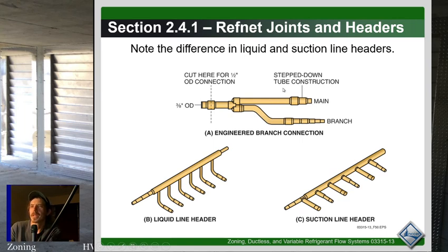Another note on these connectors, I don't know if we discussed last class, is you see how the piping is a size and then it goes up and then steps down and steps down. This is the only time where that's super acceptable in refrigeration. Sometimes your vertical piping is sized different than your horizontal piping in refrigeration, but all these up and down, sometimes you have another reducer that goes back up to another size at the end or something. Don't get too concerned about how pipe gets from A to B to C size or whatever. Reducing and increasing is pretty common on these branch connections, and it's not something to be worried about too much. Just don't do it anywhere else in your line.